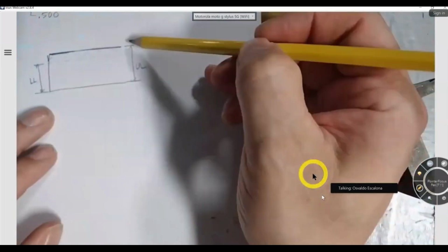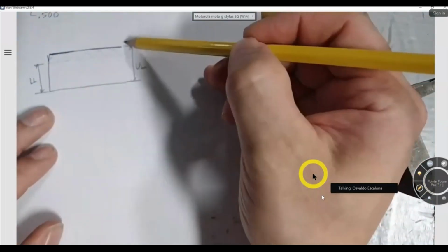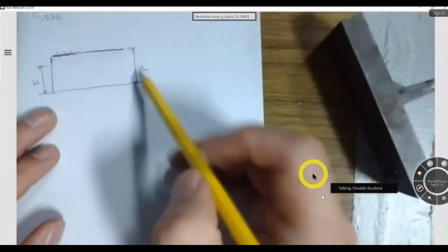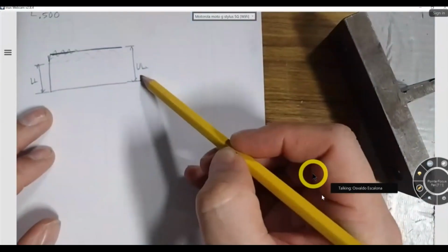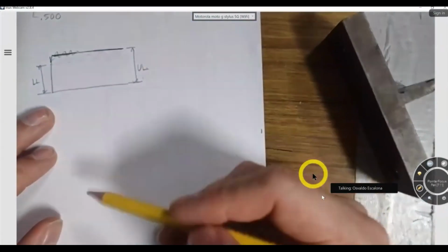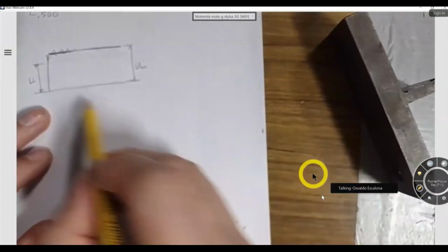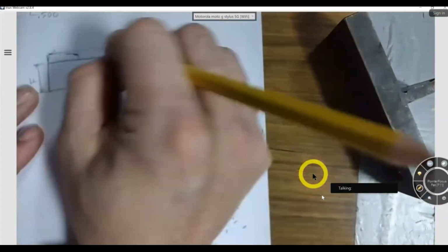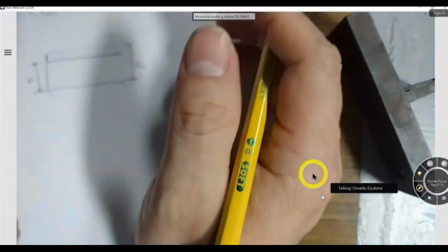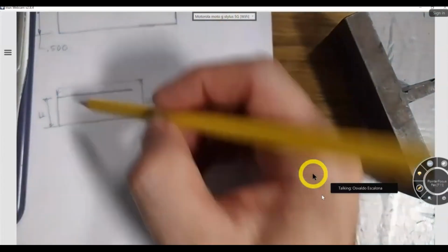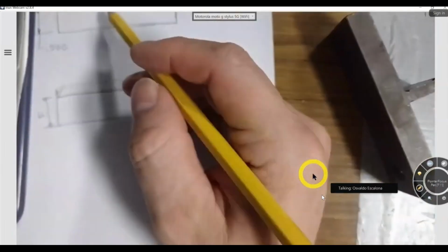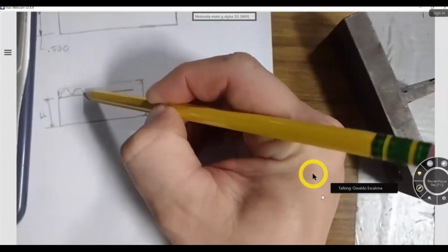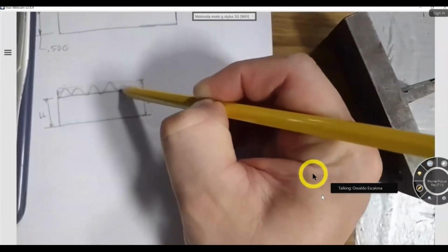It cannot have any form variation, because any variation will overpass my upper limit and then my part will not function. Usually we give it the leeway. Now, if I were to go to the lower limit, say my part came out to be that size, it will have a lot of leeway for it to go up and down. Again, sorry for the resolution. You guys see it? All right.